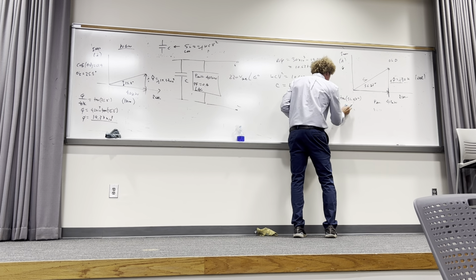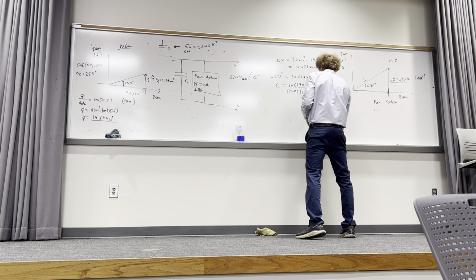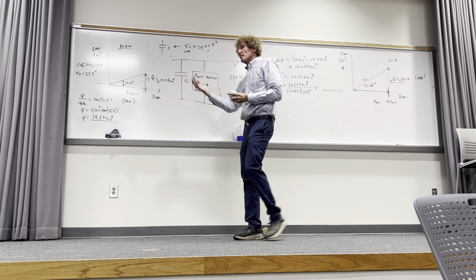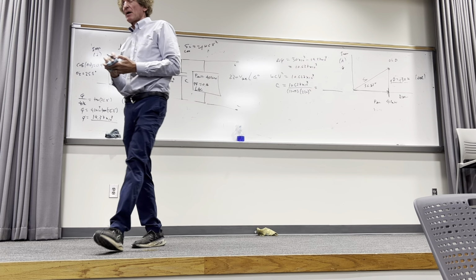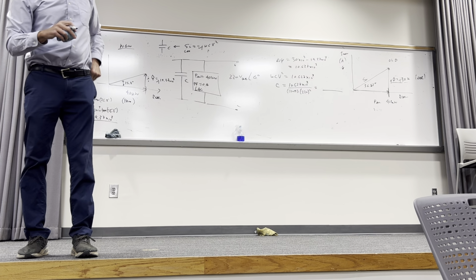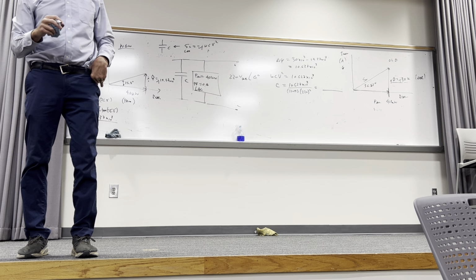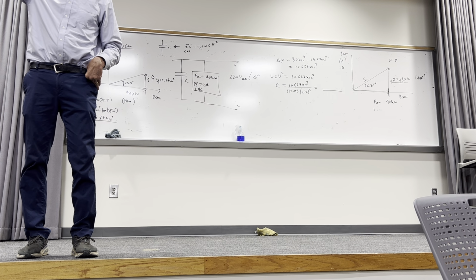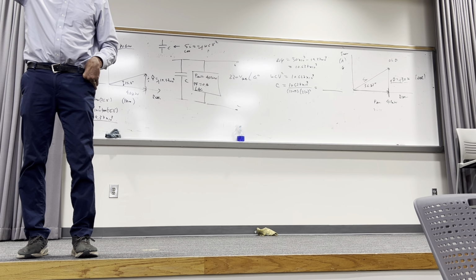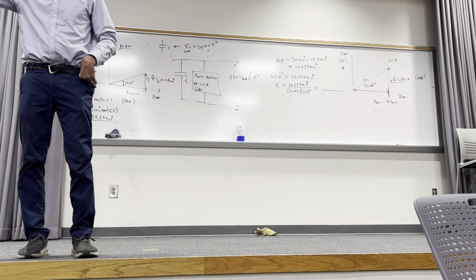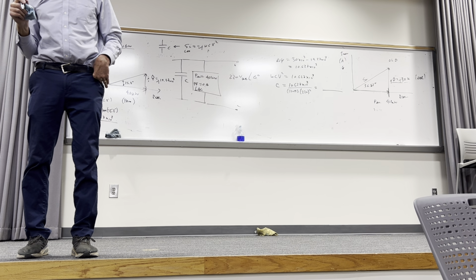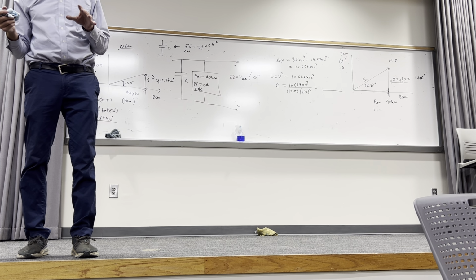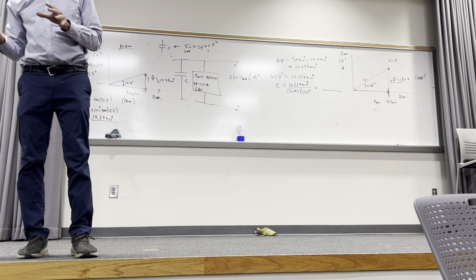And then I'm going to erase this too. So what is the value of that capacitor? And that only brings it down to a power factor of 0.9. The reason that problem is probably created by Dr. Irwin is because a lot of times those industries don't want it. I mean, the industries that used to be here, the mills, they don't want to buy enough capacitance or do enough things to bring it down to a power factor of 1. They just don't want to pay the fine.